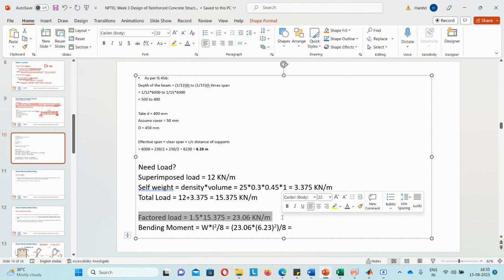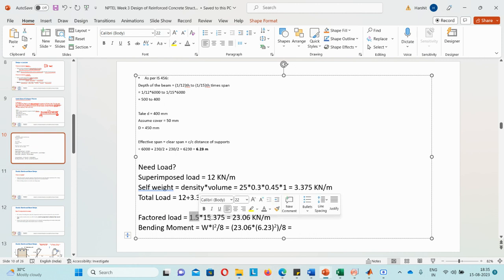So you saw in the working stress method, we only take a factor on stress, the allowable stress, but in the ultimate stress method, we factored load also, that we saw in the first live session discussion. What all factors we take for dead load, live load, and everything. So this is the factor we take for dead load. Both of these are dead load only right now. We don't have any live load acting on the structure.